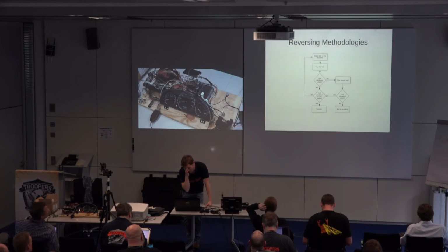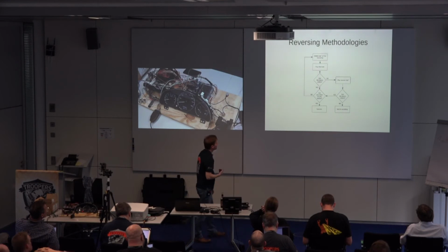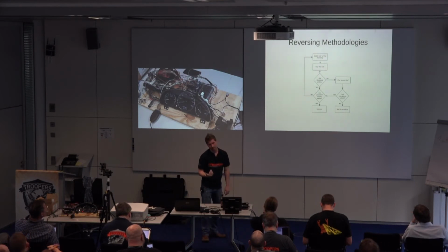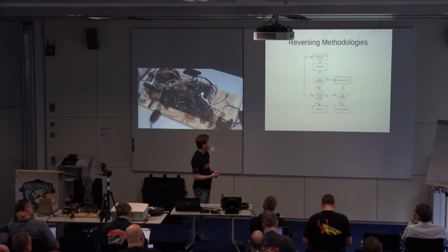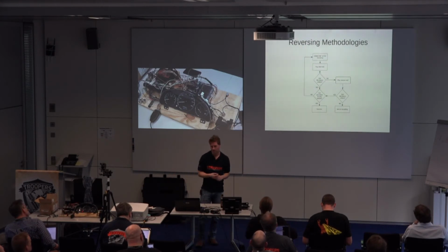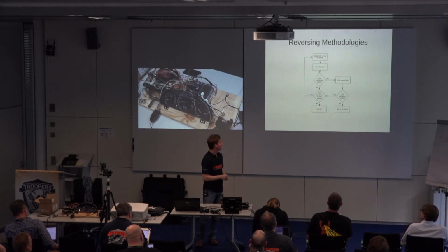Whenever I do hackathons, this seems to be the main method everybody's comfortable with. When I used the first utility, that was candump, and that just dumped everything. One of the nice things about it is you can dump whatever it is you're doing. Say if you want to reverse engineer, I think this is door locks in this example, right? Door locks. So you basically say candump, you dump it to a file, you unlock the car, you stop the dump, and then you play that dump back. If the door is unlocked, then it's in that dump. If not, then it's probably on a different bus.